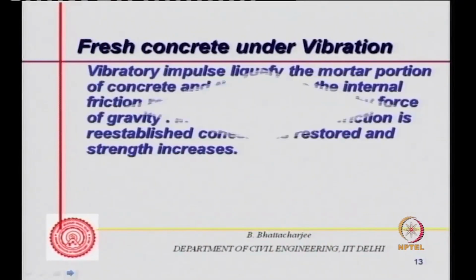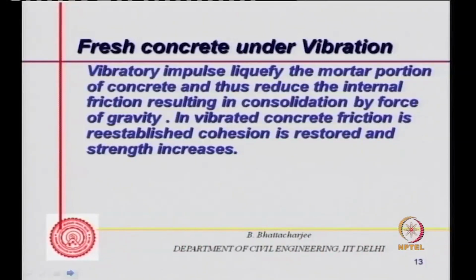So what happens? Vibratory impulse actually liquefies the mortar portion of concrete, and thus reduces the internal friction, resulting in consolidation by force of gravity. Then once the concrete is vibrated completely, the friction is re-established and cohesion is restored and strength increases.